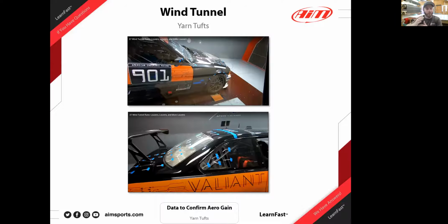And I told him the only way that happened is that the splitter's pointing up at the nose. And we're talking a flat body, maybe with tunnels, not like an actual profiled splitter you see on a prototype car or something. He ended up correcting the splitter angle, and then ended up setting the overall track record at New York Safety Track or something, I think. And he said it made a big difference.